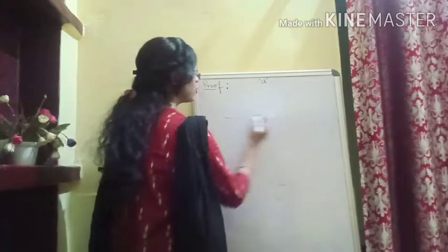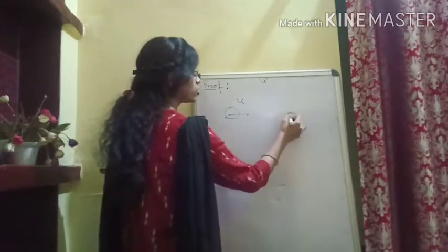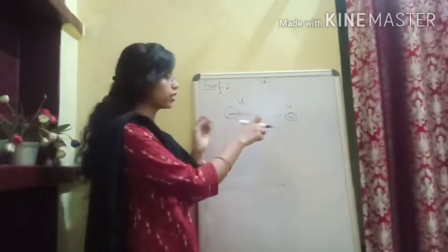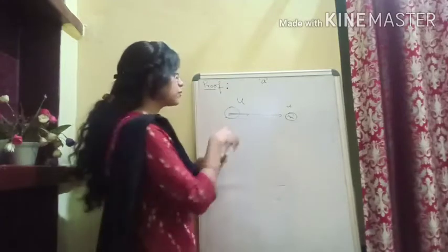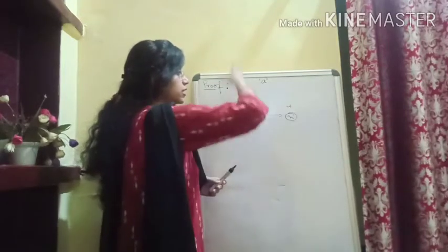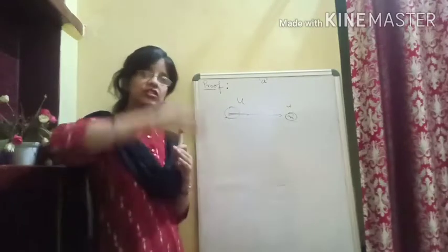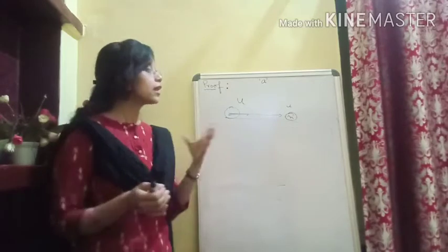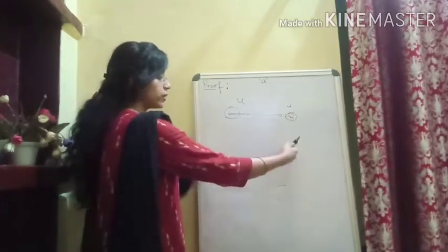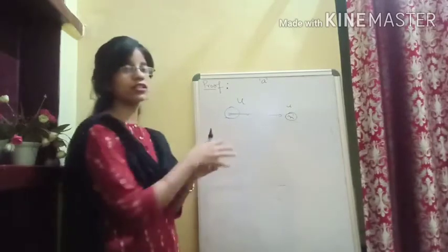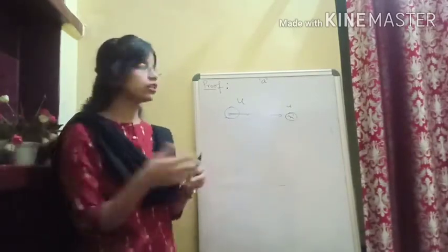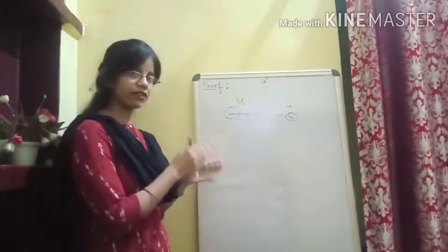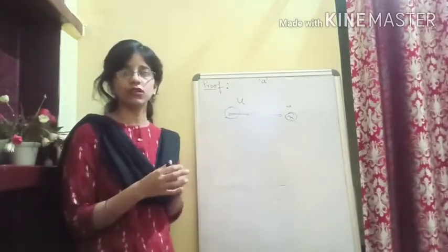Simple: when we are talking about the velocity change and everything, we are actually talking about a rectilinear motion in a horizontal direction. That means there is no motion under gravity. That means when the body is moving from this place to this place, there is no change in the height. And if there is no change in the height, position or configuration, we don't have any change in the potential energy. So there will be no change in potential energy, only change in kinetic energy, and that's why we have the expression for change in kinetic energy equal to the work done.